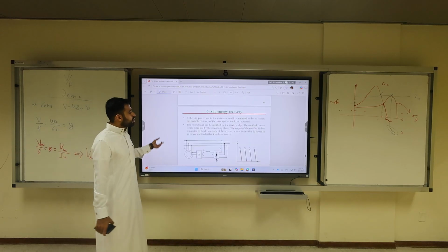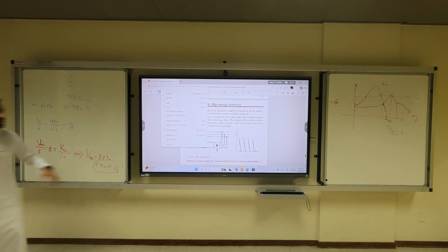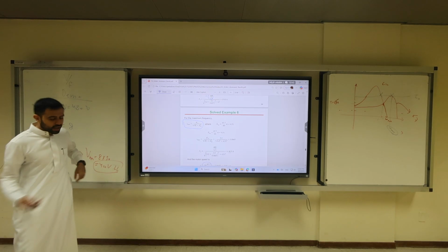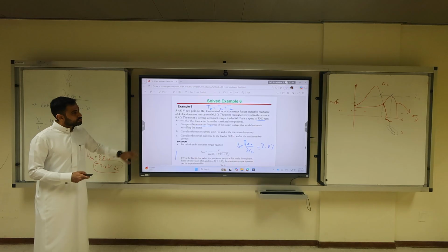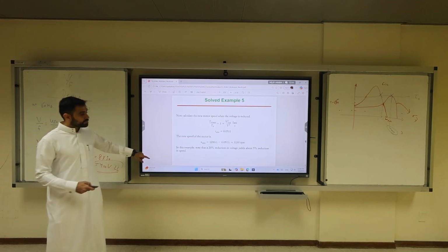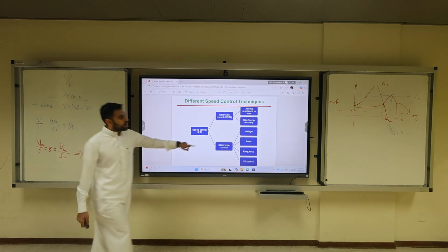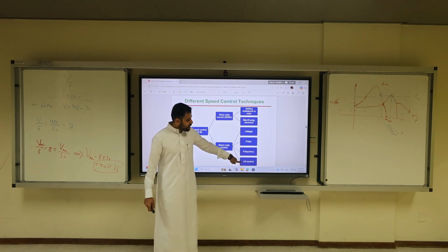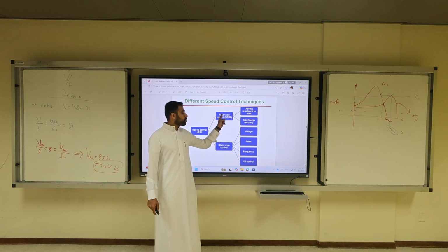Okay? Now, let's talk about the last. Let's go back to all the previous techniques. What did we have before? You remember? One, adding resistance. We talked about adding resistance, talked about voltage, talked about poles, talked about frequency, and we talked about V over F. The last one is our most preferred one, slip energy recovery, if you want to control the rotor side.